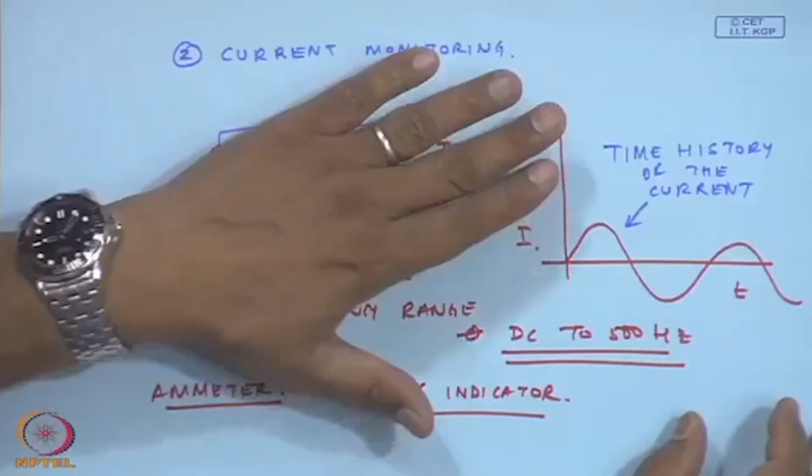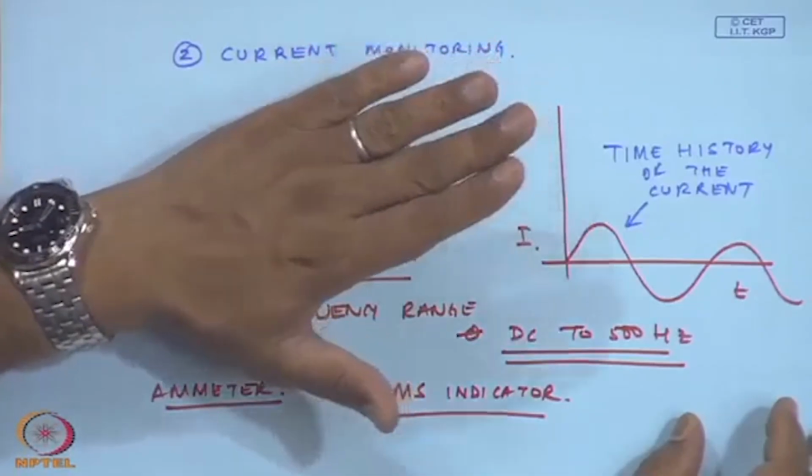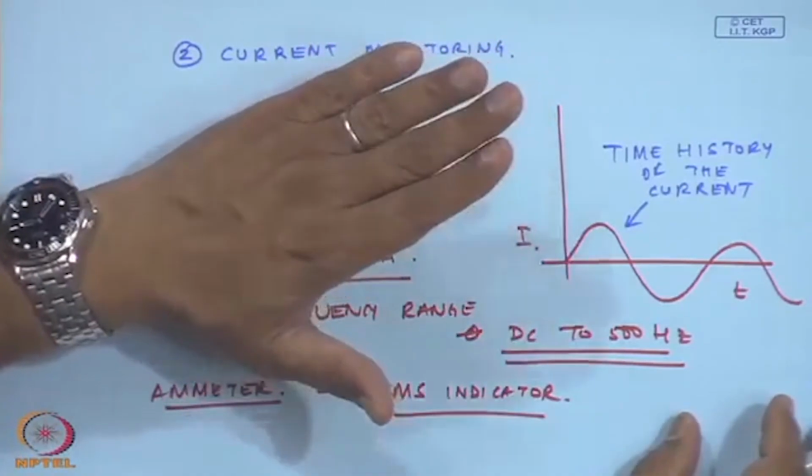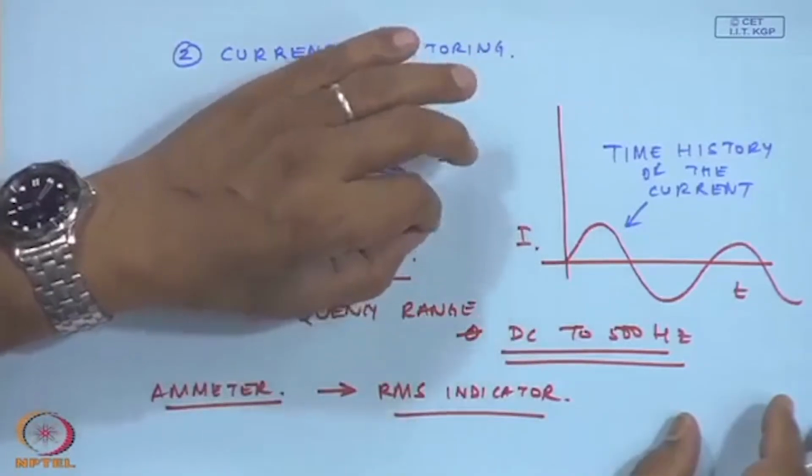If I do a vibration monitoring, I am not sure that sometimes I will get sidebands around supply frequency. That may not happen. Okay, I may see only the peaks at supply frequencies and twice supply frequency, but that is why measuring and monitoring current has become a very powerful and convenient technique of monitoring the motor faults.